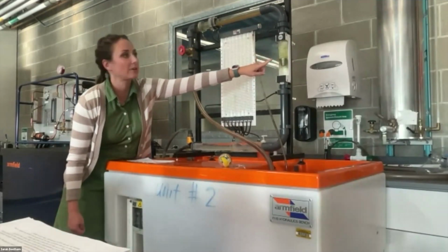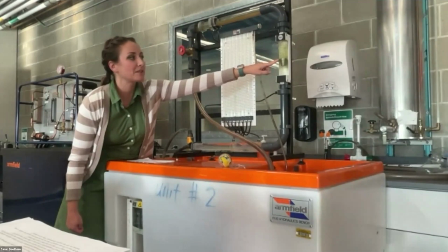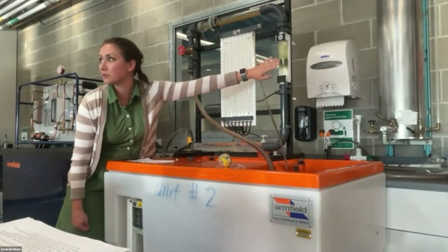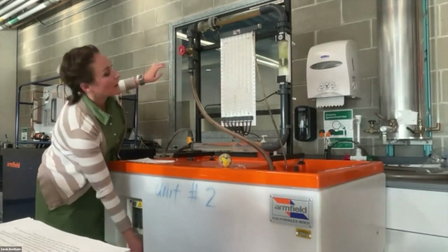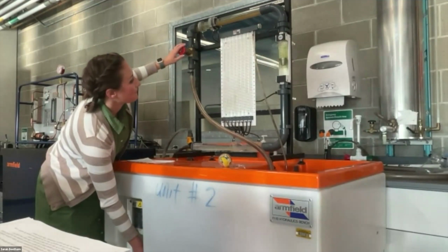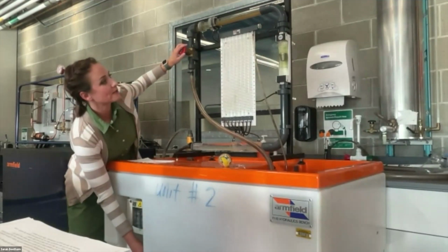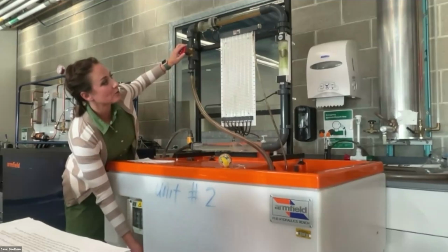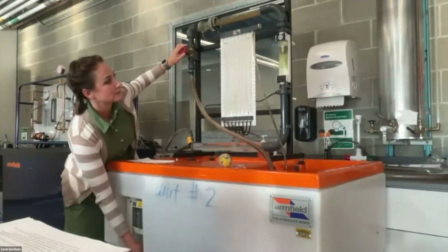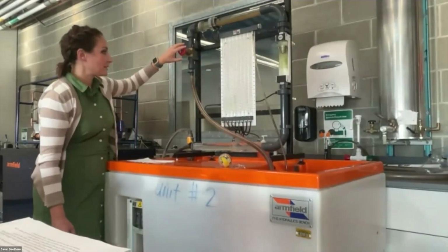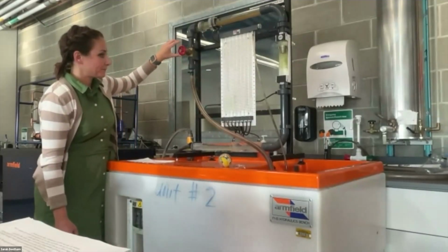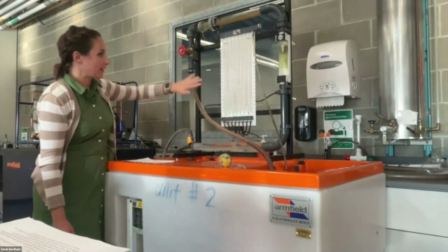Actually, just to clarify, the top of this surface is where you're going to read the flow rate off of, not the bottom. And so typically you want to start at the higher flow rate. So you're going to be collecting values between, I think it's 5 and 20. So 20 is the top of this. Okay, this is actually pretty okay.